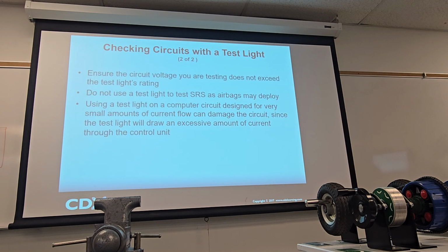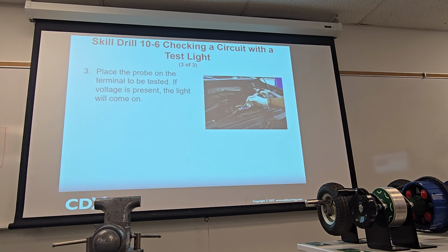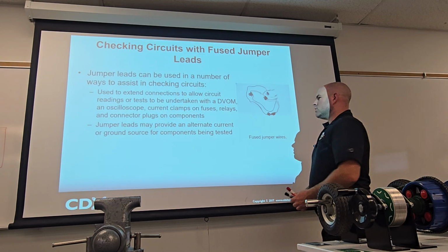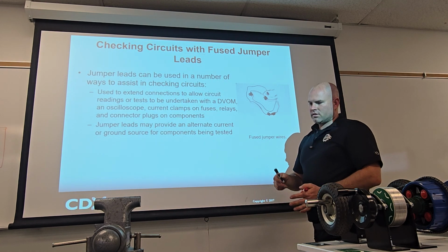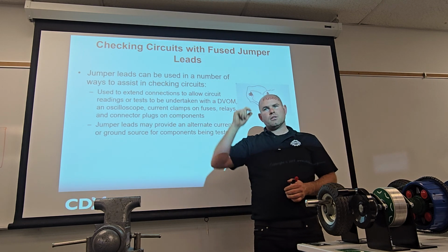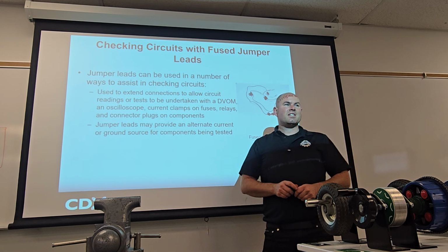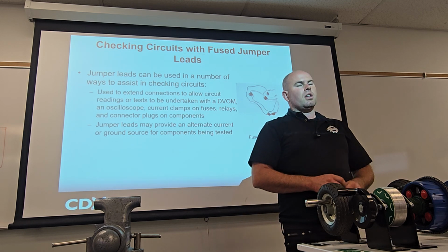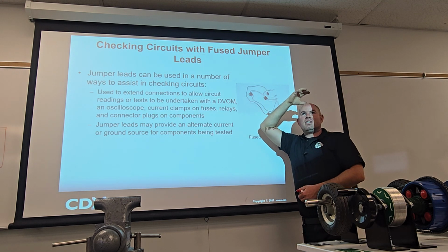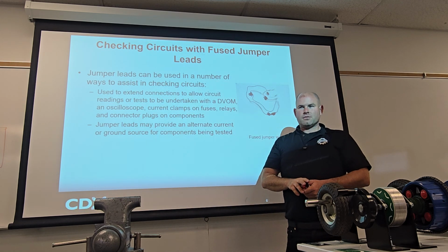Okay, so here's kind of like showing you how to do it, right? Testing fuses, for example, that's all legit. You could do it. Okay, now another tool, as we talk about it, jumper leads. Okay, did anybody do any kind of jumper stuff when we were troubleshooting the boards? Because a couple of you had some bad components. We did some jumper leads and stuff, didn't we? Now this says fused jumper leads. In a jam, sometimes I'll use unfused. You understand what the negative of unfused is, right?